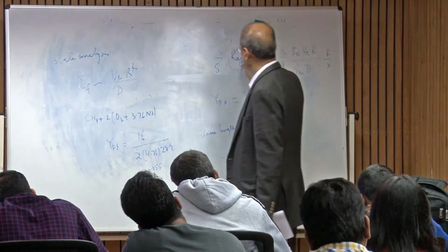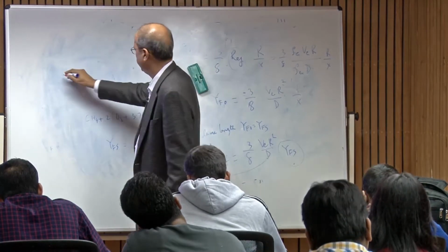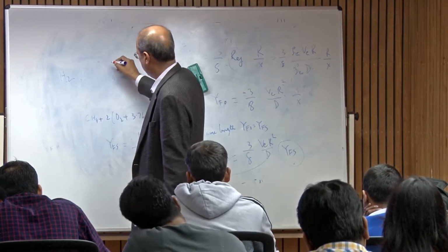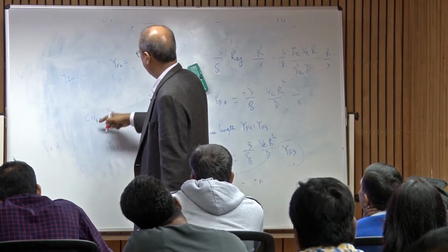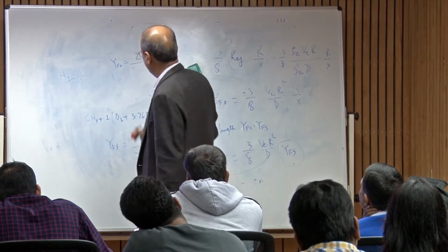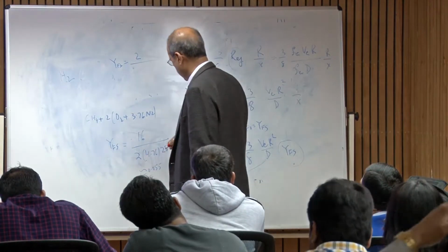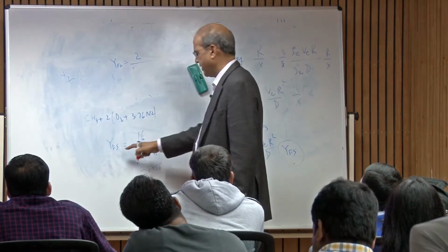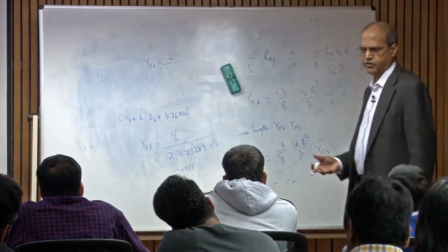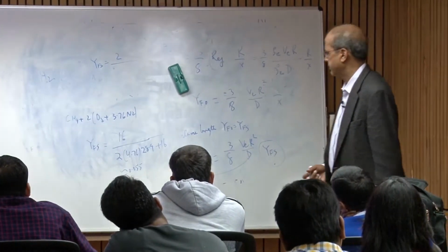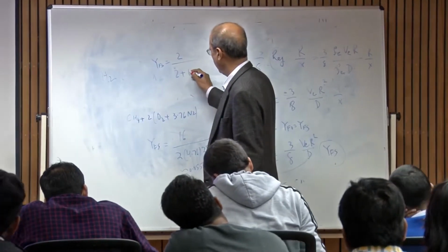But if you take hydrogen, this value is smaller. So now for hydrogen, this is 2. Oh, wait a minute, this is not correct, right? This is YF, so we have to add 2 in the denominator also. It's the mass fraction of fuel. So this will be 2 plus the mass of air.